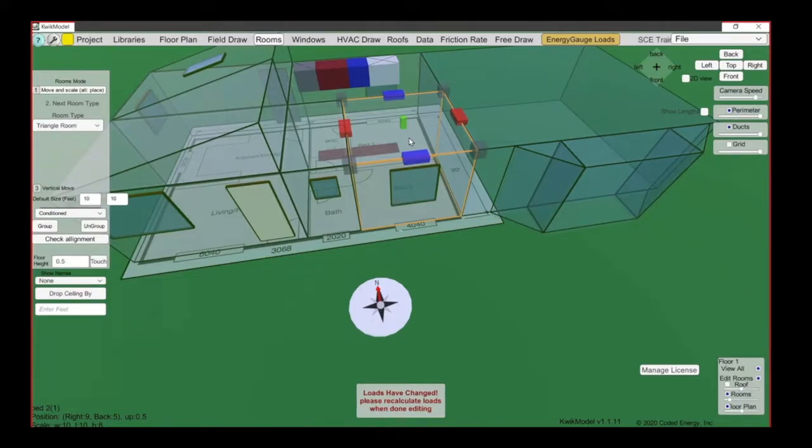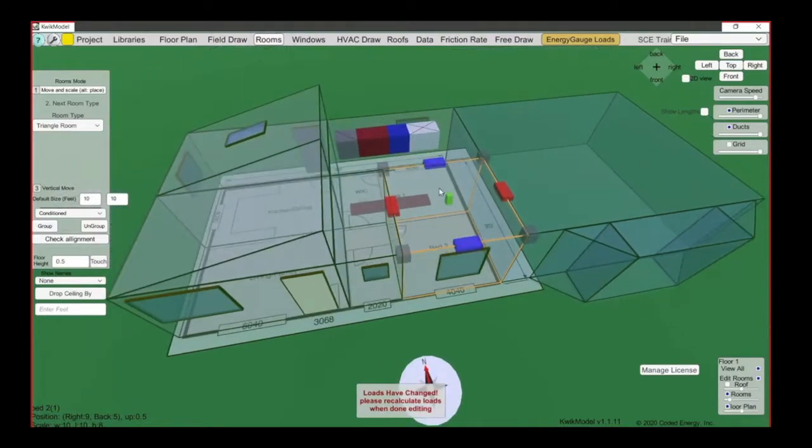And then there are some other things having to do with static pressure and stuff like that, but it'll tell us how much airflow we have to work with. And then the software will know those percentages, and it will divide that airflow up for us and say, okay, this room needs this many CFM, that room needs this many CFM, and so on and so forth, okay?